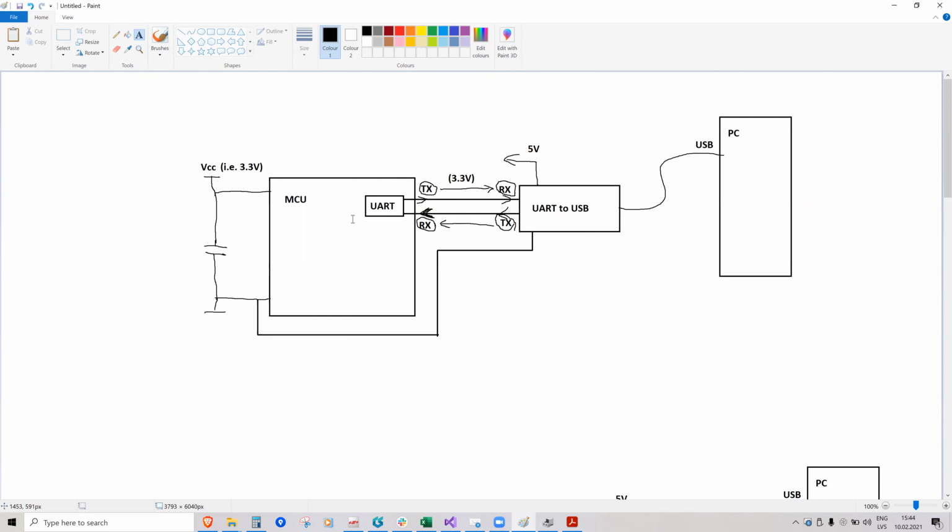Then you just send the data forth and receive it back, and everything works. In the microcontroller, you just give the UART peripheral a new byte to send, and it sends it out and sets a status bit in its register that it has completed sending. When it receives data, it can make an interrupt in the microcontroller and give it the new byte that it has received. You will do this part in the lab.